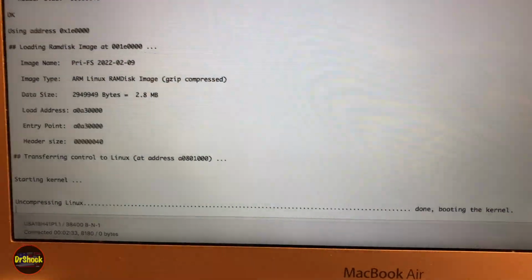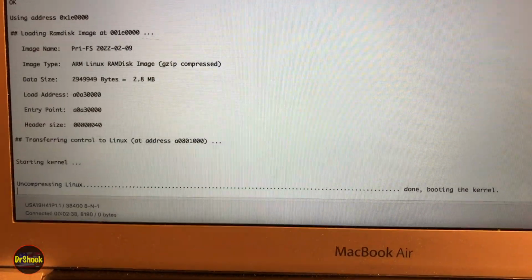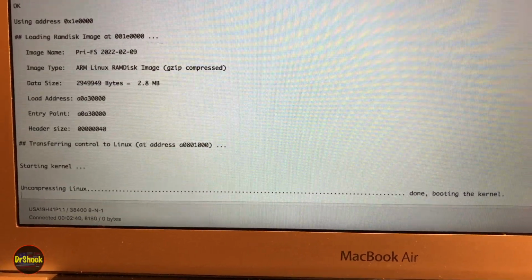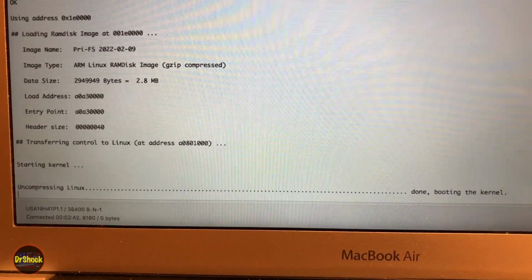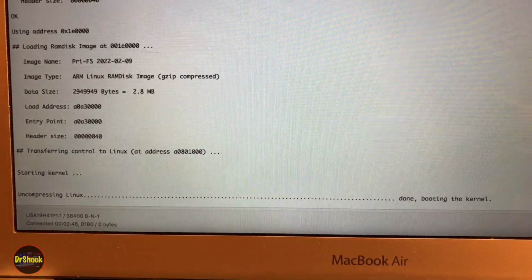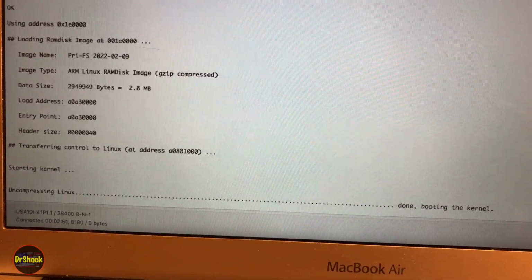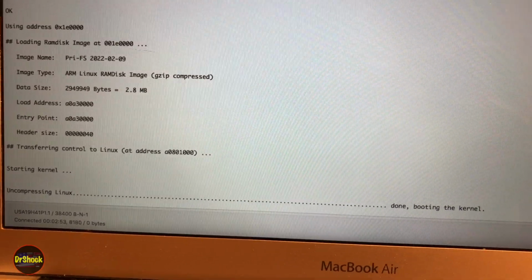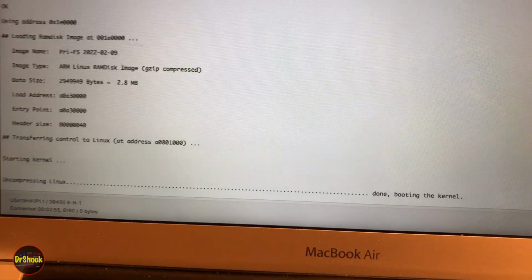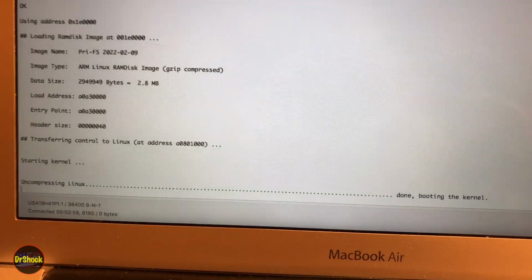And what we find on this one is we never get past this step of booting the kernel. So this tells us a couple of things. One, we never even ran the post. We never even got the kernel booted up successfully, and the whole hardware device is locked up. So this is a problem that's more fundamental, where the processor on board is attempting to access some other piece of hardware inside the device and is getting a hard lockup, so it's dead.